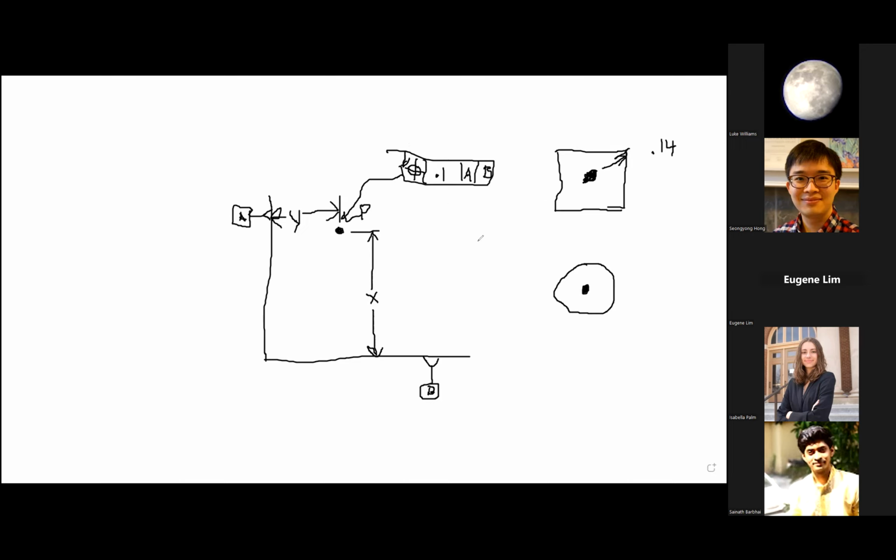this allows us to say to the machinist, no, we don't want this. We don't want this box that this point can meander about. Instead, we want to have this circle where the radius of this circle is 0.1, and that is the region that is okay for this feature. So this is a much more specific way of talking about how you want to control your feature within a drawing.